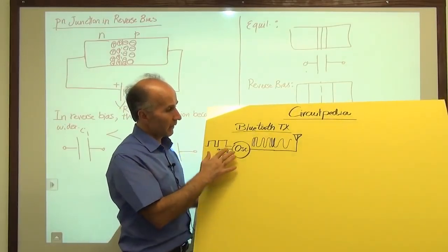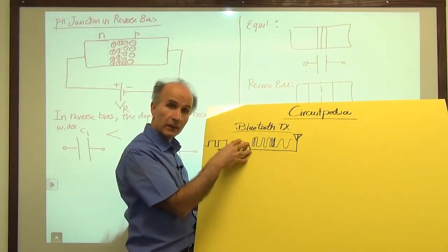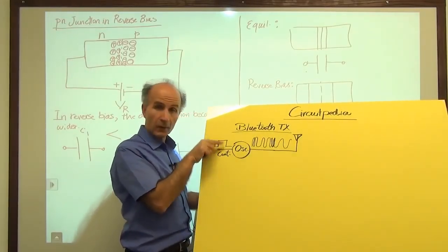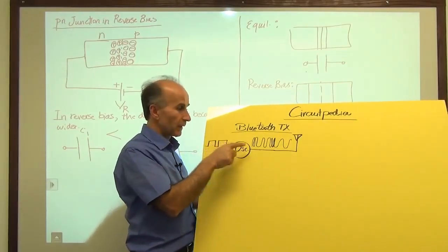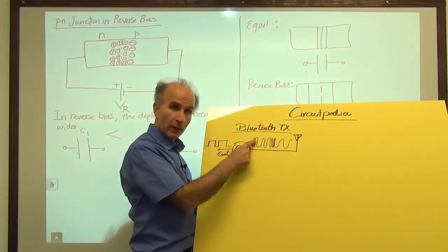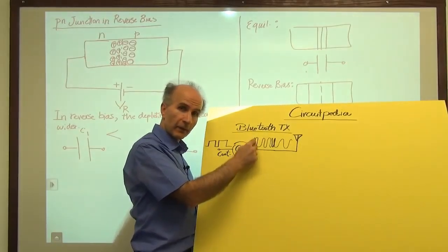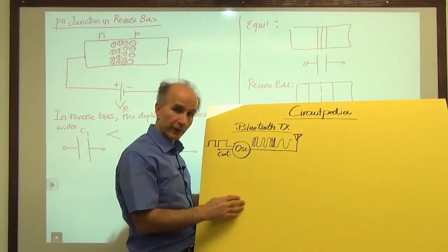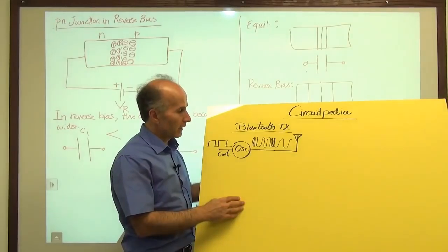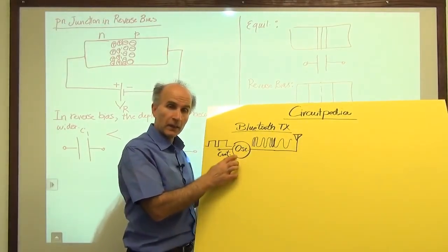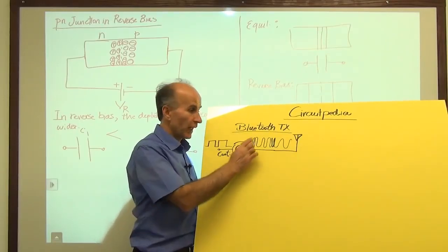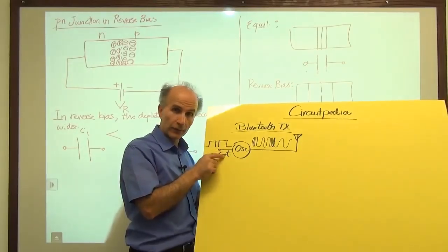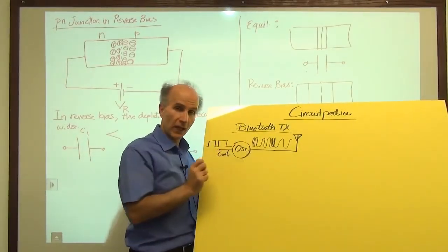So we said that the transmitter consists of an oscillator with a control input. And when the control jumps between 0 and 1, let's say 0 volt, 1 volt, 0 volt, 1 volt, the output frequency jumps up and down: 2.4 gigahertz plus a small amount, 2.4 gigahertz minus a small amount. It just is a small perturbation around 2.4 gigahertz. Now this oscillator needs a mechanism to change its frequency. And this control voltage causes that frequency change.